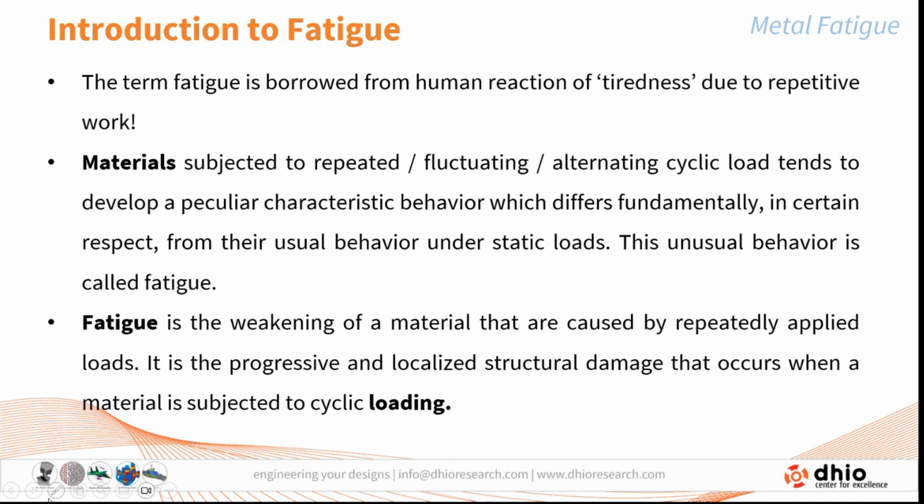Whereas a fluctuating load is the type of load which initially starts from 0 and reaches a specific value of tensile loading, let us take about 20 Newtons. Then it is subjected to a compressive loading of 10 Newton. That means the sense of loading changes after a certain duration of time. If this keeps repeating, you call such a load a fluctuating load.